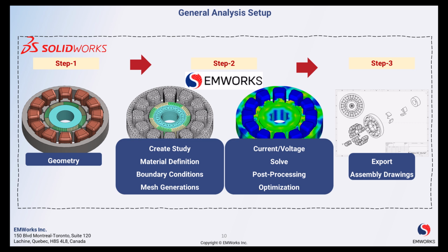Then, automatic and adaptive meshing tools discretize the geometry into finite elements suited for numerical analysis. With the model set up, multiphysics analysis can be executed to characterize electromagnetic, thermal, structural, and dynamic performance under operating loads. The parametric architecture enables design optimization by modifying variables like geometry, materials, or excitations and rapidly resimulating. Comprehensive visualization and reporting features also allow convenient sharing of insights with decision makers. This efficient process facilitates virtual prototyping of electrical and electromechanical systems with a high degree of accuracy.